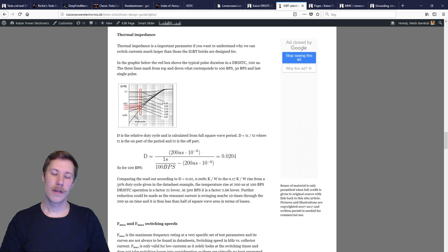When you do parallel diodes, it was never recommended to go higher than 30% above, because when you have no control of your real bus inductance, you have no control of where your current goes. So never assume that you can conduct twice as much current with twice as many IGBTs.